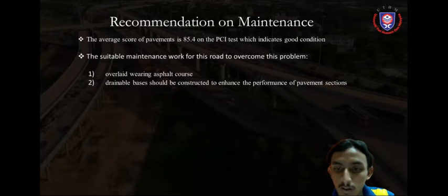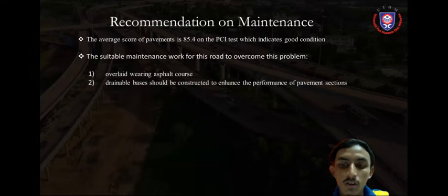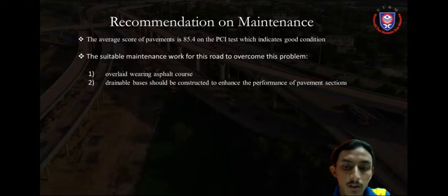Overloading and lack of proper road maintenance are major causes of pavement deterioration, and are the most common causes of alligator cracking, potholes, longitudinal cracks, bleeding, and edge cracks. This deteriorated pavement might be hazardous to road users. To ensure the safety of road users, the pavement condition index, PCI, should be utilized to identify the pavement condition of the investigated road that has pavement distress.